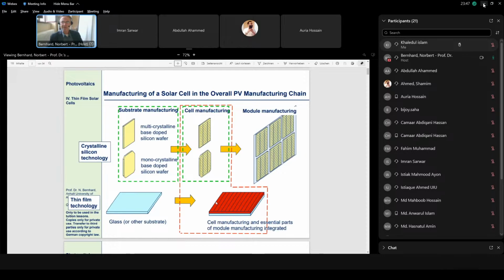And the reason why this is done are the different absorption coefficients and also the different band gap of the material. You see the dotted line, that is a crystalline material. And we see the typical shape of an indirect semiconductor. Here the dashed line is amorphous silicon, and at least this steeper increase already resembles a little bit a direct semiconductor, and that is why this material is called a quasi-direct semiconductor.